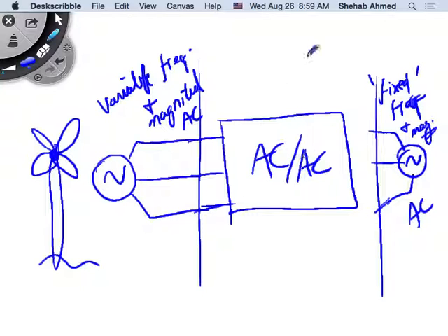So a MOSFET. A MOSFET moves current in one direction, and voltage is in one direction. If you flip the voltage, the MOSFET will not work. Current cannot go in that direction because there is a parasitic diode. Even if the voltage is flipped, you will not be able to control things because current will just flow because of the diode. Even if there is no diode, current cannot go through in reverse through a MOSFET. Right? So there is no bidirectional switch.